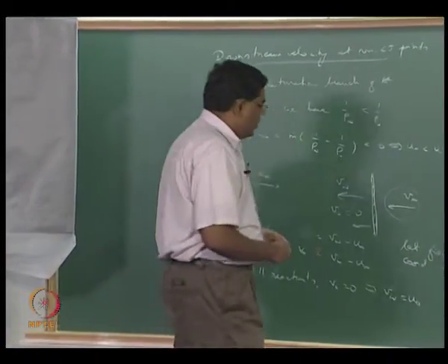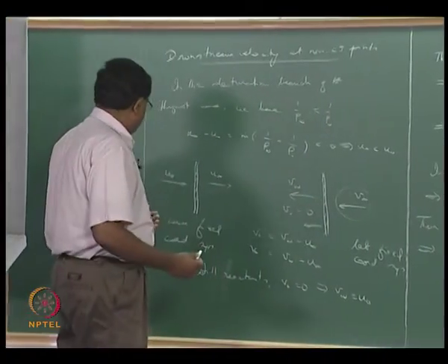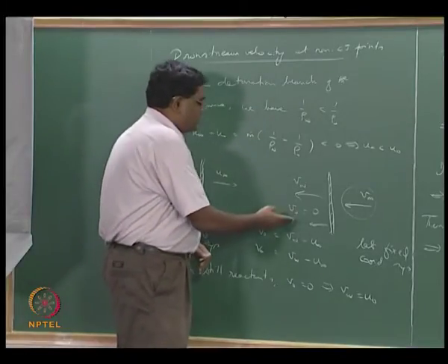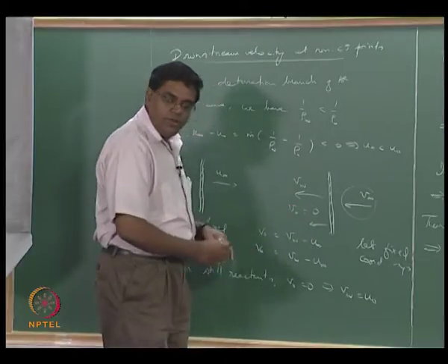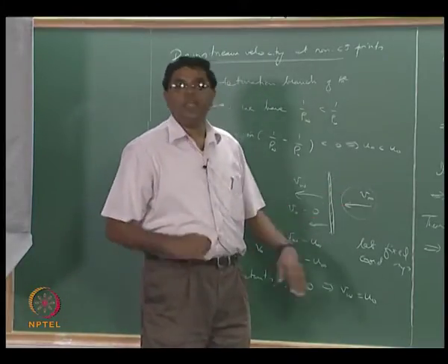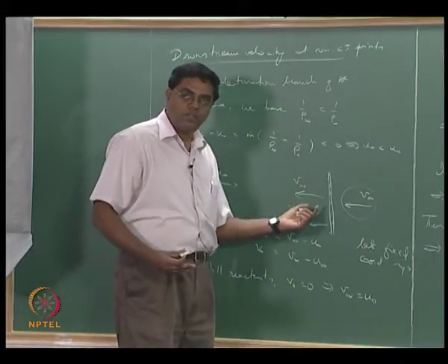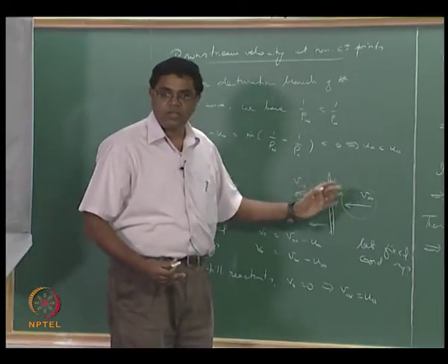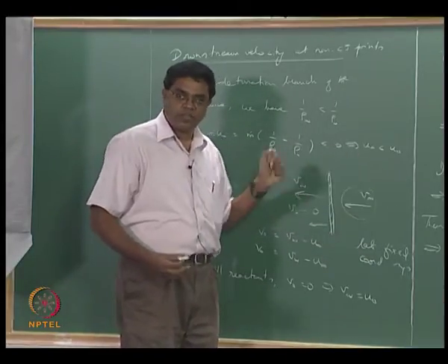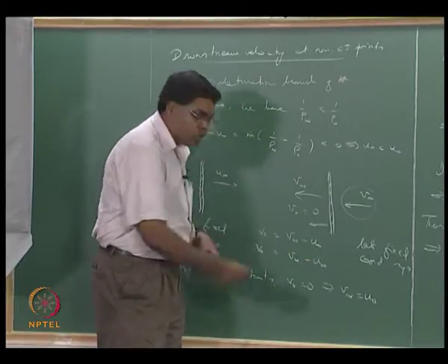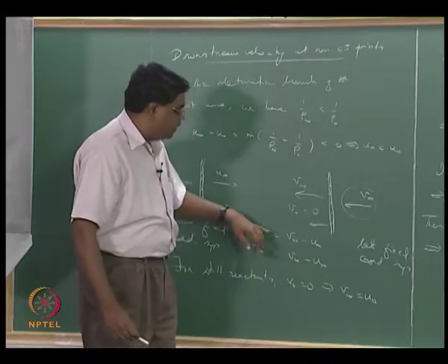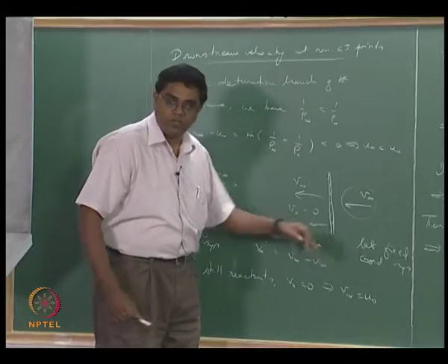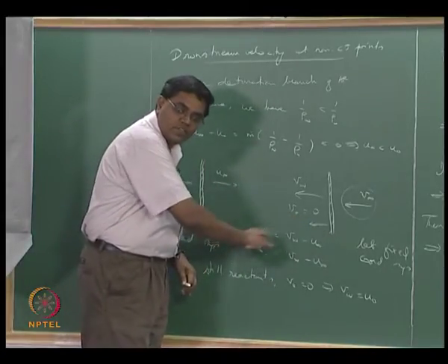All right, so you can work that out. Maybe what you do is you assume that V0 is going to be positive in this direction, V infinity is going to be positive in that direction. You should be able to show that if you were to make V0 equal to 0, then V infinity becomes negative for detonation wave and it's positive for deflagration wave. That will simply make this different. You would now say that V0 is equal to U infinity minus VW, and V infinity is equal to U infinity minus VW. That's how you will actually get these signs flipped.